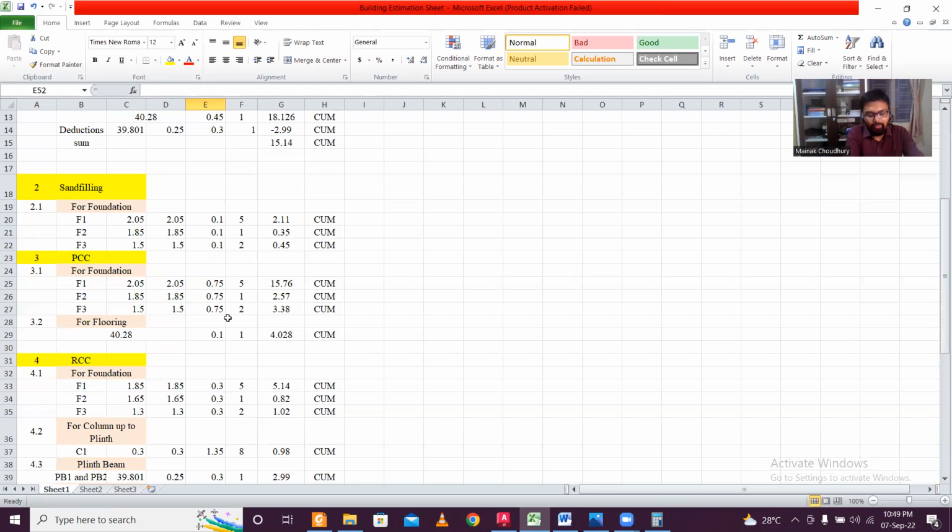Actually, as per my opinion, you can make the outer wall and inner wall thickness the same, 4 inches or 5 inches, whatever the thickness of the brick, because the structures which you are making are frame structures, and the brick is only acting as a partition. So you can have a 5-inch wall easily mainly for the initial building. If you are concerned with additional safety purposes, you can go for a 10-inch wall, or this thicker wall. No problem in that.